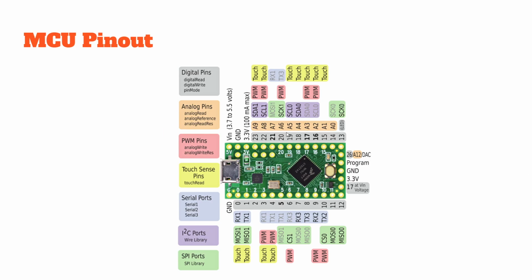These orange ones are called analog pins. It looks like there's 10, 11. I think there's one on the underside of this, 12, maybe more, 13, I don't know. Analog pins are pins that don't send digital info, they send a continuum of info. You can simulate a sinusoid, a ramp wave, any info that would need more data than just a 1 or a 0.